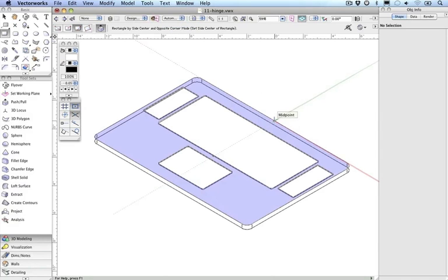Move your cursor to the midpoint of the top edge of the CPU case. Once the top face of the case is highlighted in blue and the cursor cue midpoint is displayed, click to start drawing the rectangle. We need the width of the hinge to match the keyboard width, which is 11 3/8